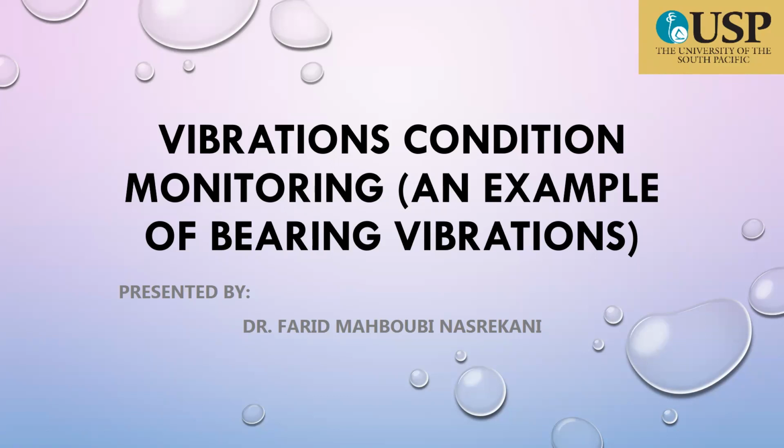Generally, we use vibration monitoring, in fact the experimental test for vibration, for two main purposes. The first purpose is to extract the characteristics of a system. For example, we use accelerometers or a modal test to extract the first natural frequency of a system, and also the damping ratio in your structure.